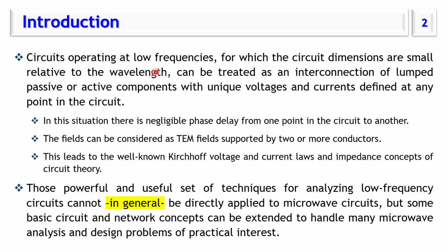At lower frequency, the dimensions of components are much smaller than the wavelength, so there is no phase variation for current nor for voltage across elements. We can define a unique voltage and current at any point in the circuit, and we can apply what we know about circuit theory like Kirchhoff's law, Ohm's law, Ampere's law, and this is very useful and powerful in analyzing circuits at low frequency.